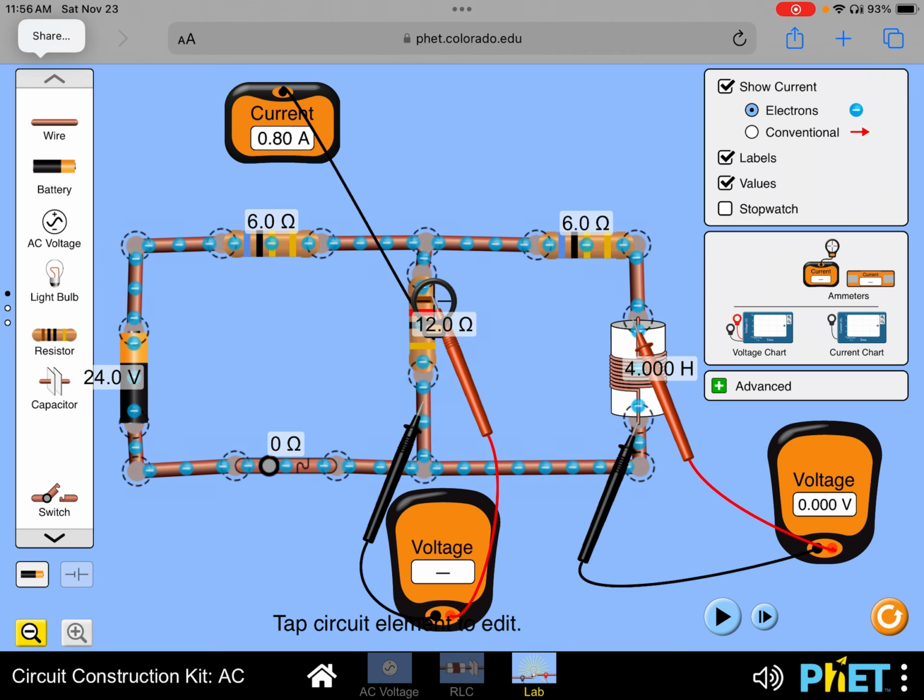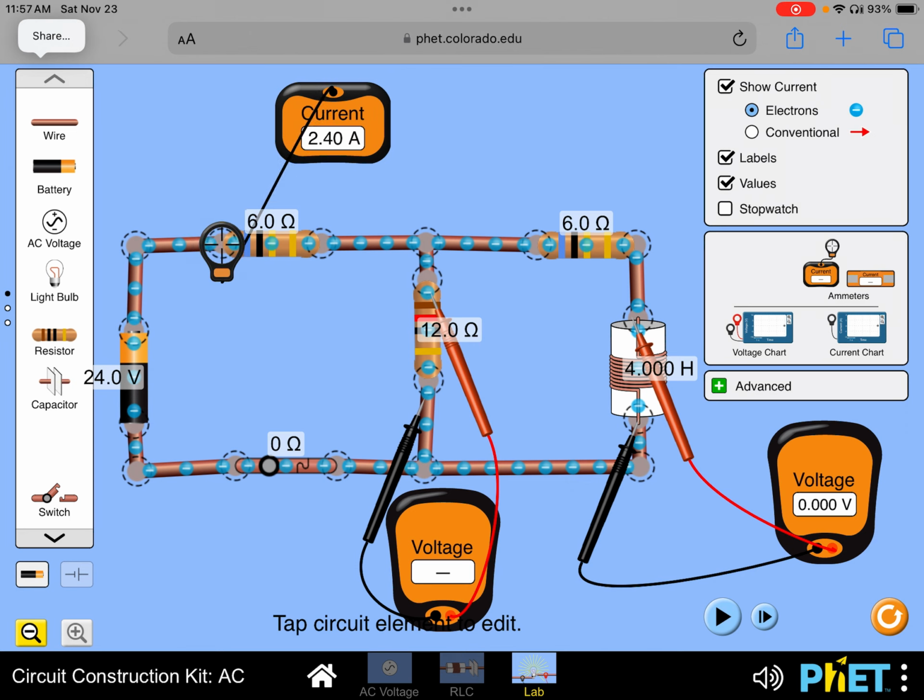in the section with the inductor is just then the current that you would have if the inductor would be simply a wire. So 1.6 amperes, in the central branch 0.8, and the sum of the two, 2.4 amperes for the total current. Now I open the switch.